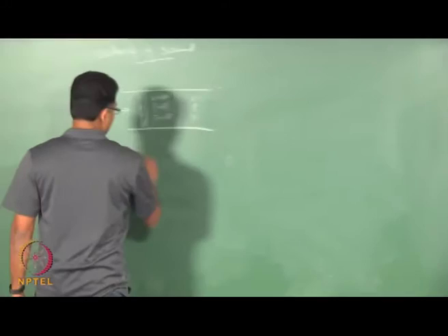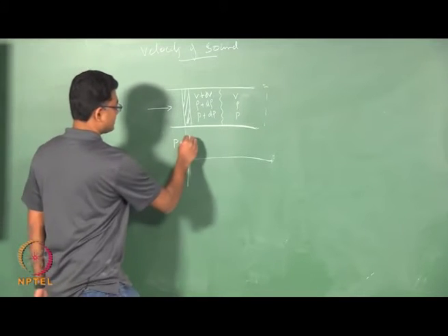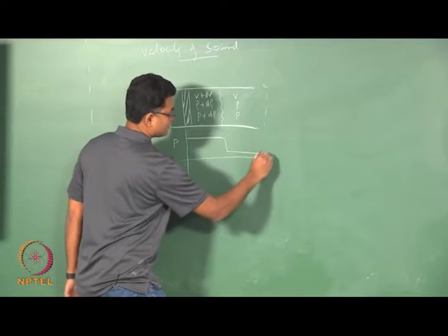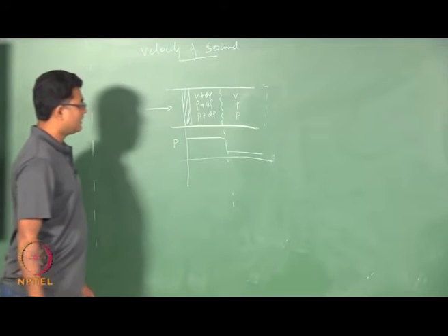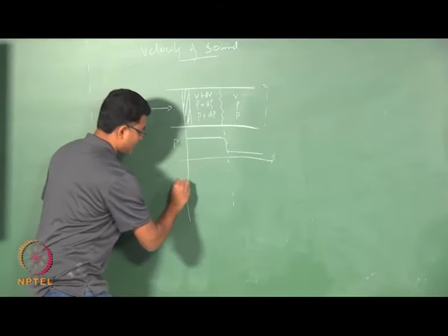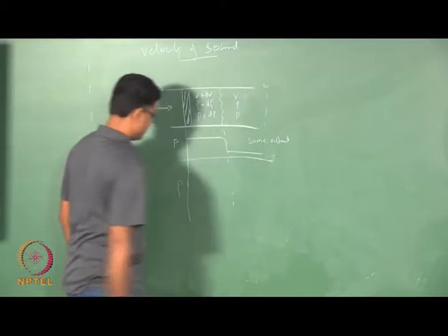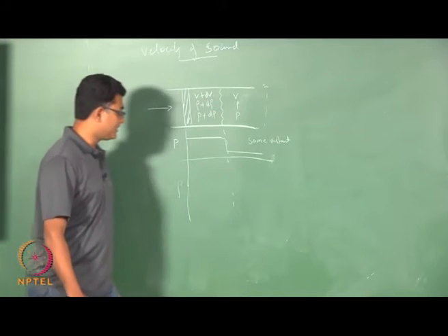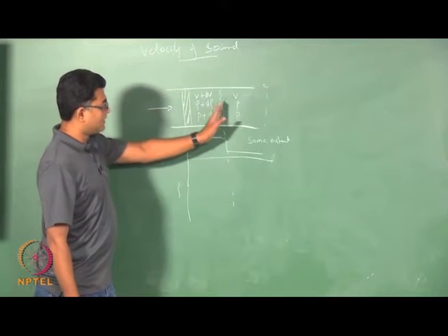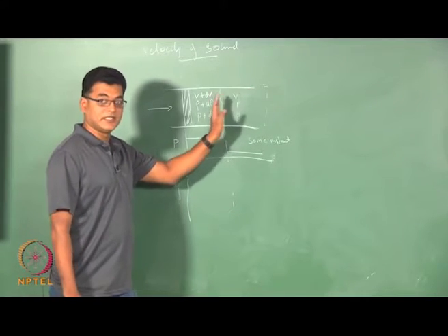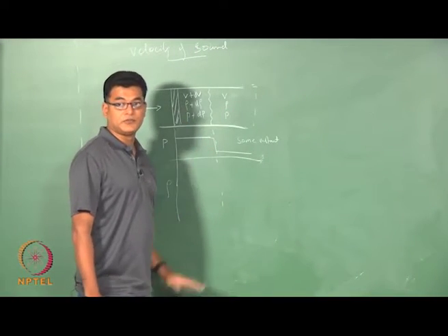So, if I draw the pressure at this instant, the pressure would be higher in this region, then suddenly it drops to some other pressure. Okay. So, this is the pressure in front at the wave front. It is a snapshot of the process which we are going to discuss. Same is the case with density. So, the density would be large here, and then as the pressure front moves, the density keeps transmitting to the region where it is not affected by the piston movement.